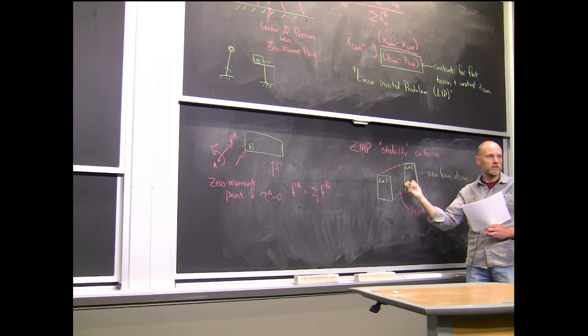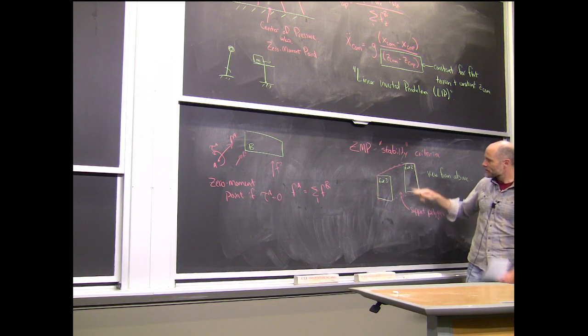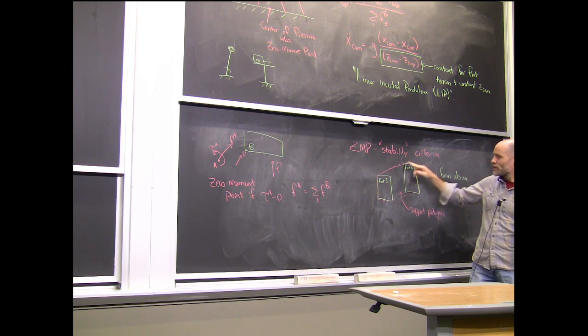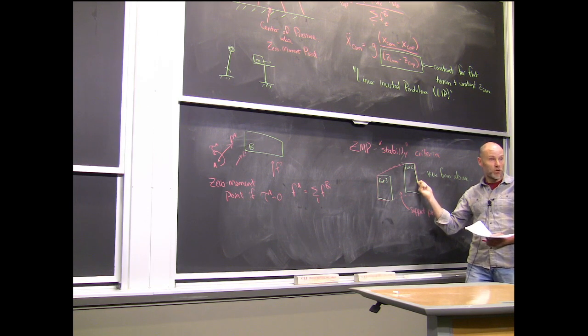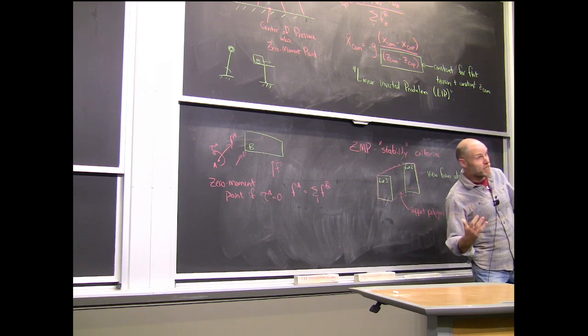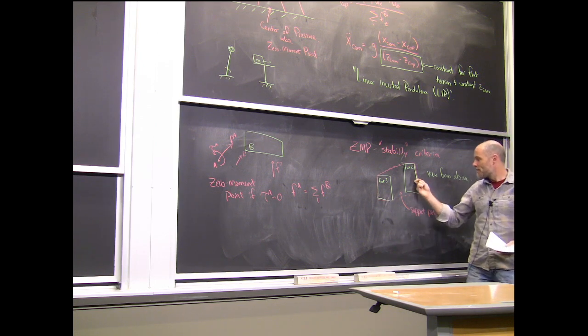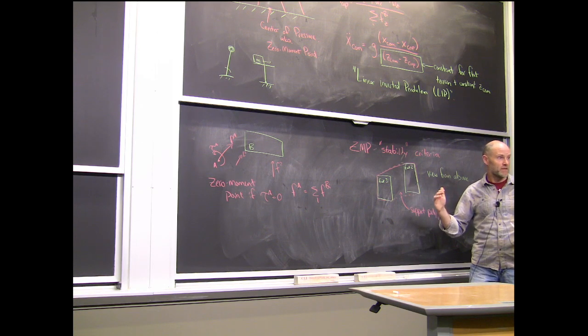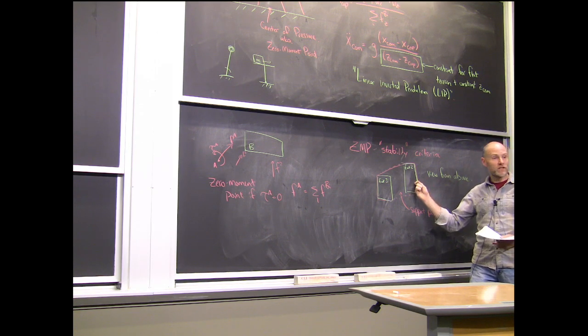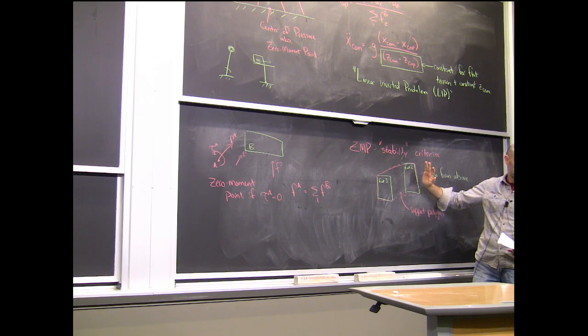Is that sort of clear? Okay, if I'm looking down, the center of pressure should always be inside my support polygon. When the center of pressure hits the edge of my support polygon, then there's a chance that I'm tipping, okay? If my center of pressure is even a little bit inside the support polygon, then I cannot be tipping. Because in order for my center of pressure to be inside this support polygon, that means I have to have had as much force happening on this side to balance something and pull it into the inside, so I cannot be tipping around my foot.